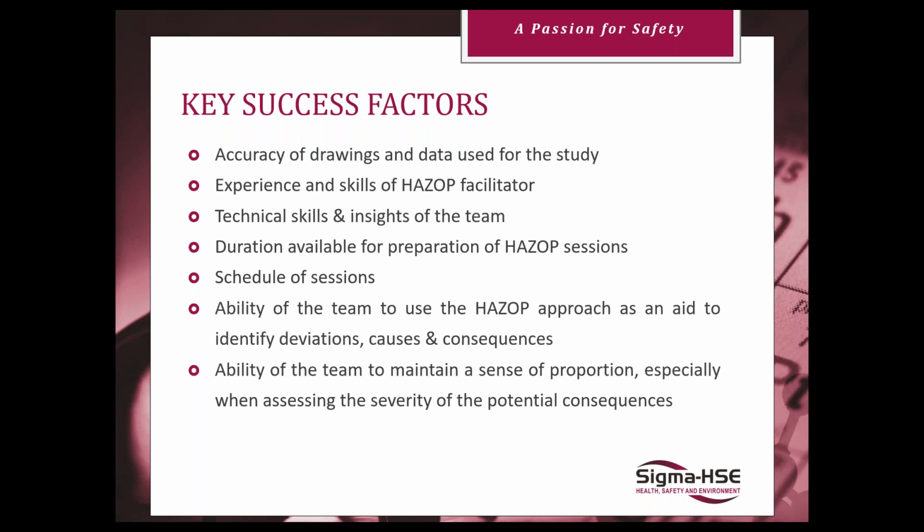And you want to make sure you're maintaining a sense of proportion, especially when assessing the severity of your potential consequences. You don't want to end up on the side where you have the potential for a vessel rupture at more than 3 times the max allowable working pressure, but the team's trying to say it would only result in a first aid. And you also don't want to end up on the other side where you may have a leak on a water system and you're saying there's a potential fatality, if really it's just that you might have some environmental impact from dirty water making its way to runoff. You want to make sure you're keeping your eyes on the goalpost and keeping it centered and realistic.